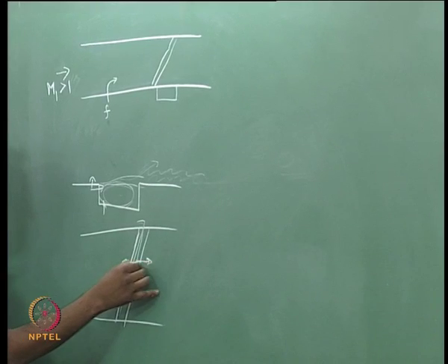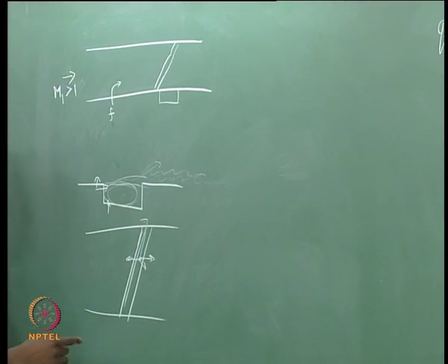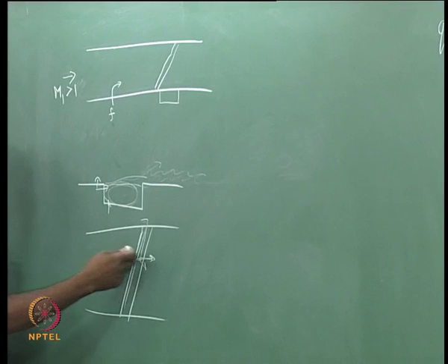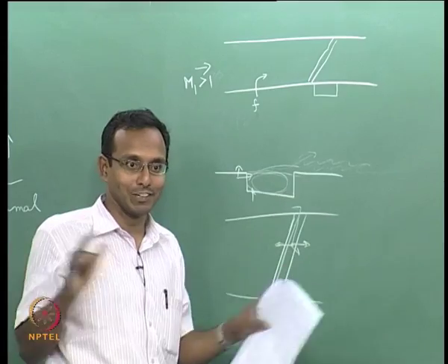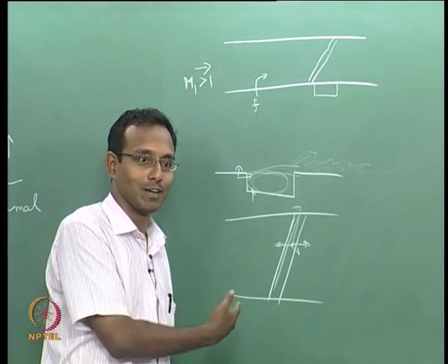If I inject along the flow, then there is a problem that they are all going together, the velocity difference is less, shear is less, and it is not going to mix very well. So they have to think about perpendicular injection or against the flow injection typically. When I do that, I am fighting the flow if I inject against it, so the P naught loss will be a little higher. Okay, I am trying to link all the things that you have learnt in gas dynamics till now in this one application.